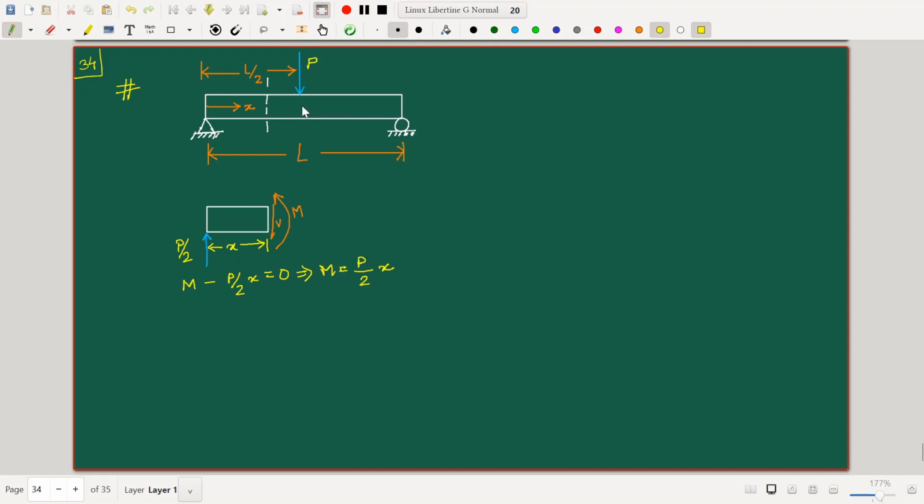So exploiting this symmetry, for our deflection, which in general is del del P of the integral from 0 to L of M squared by 2 EI, this basic formula remains the same for all beam problems.